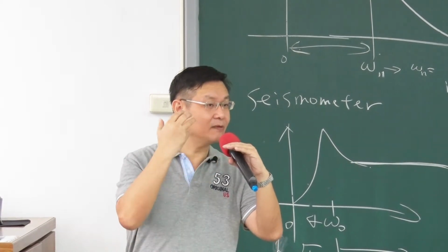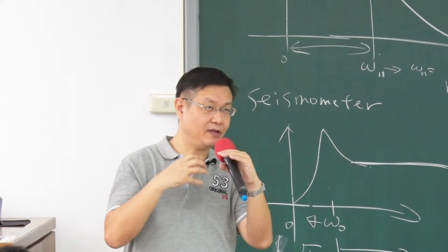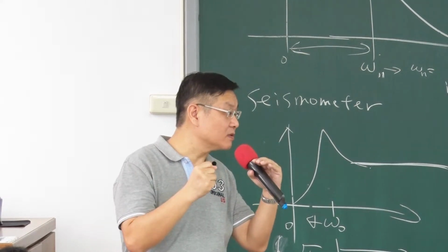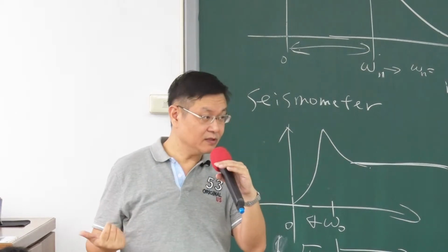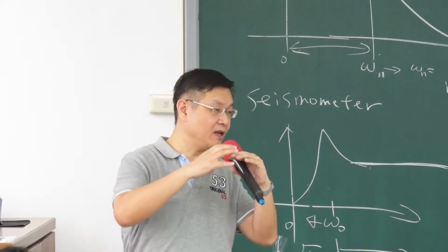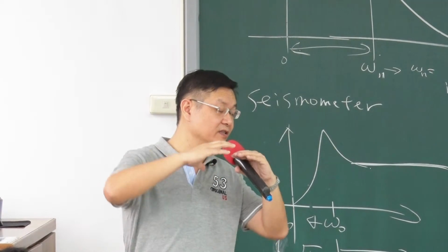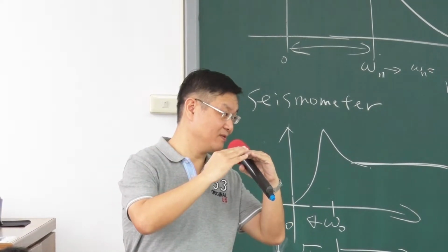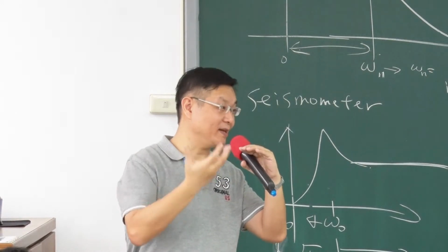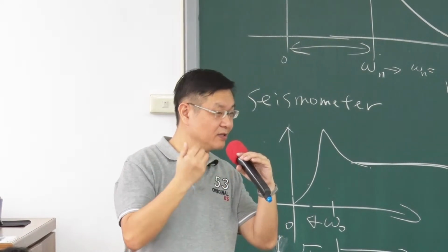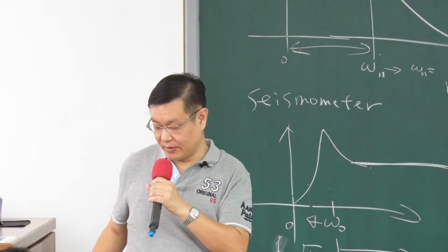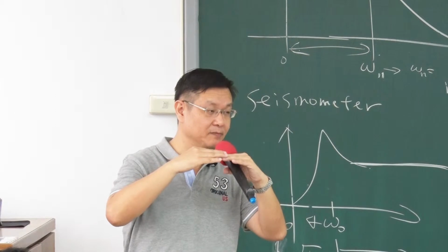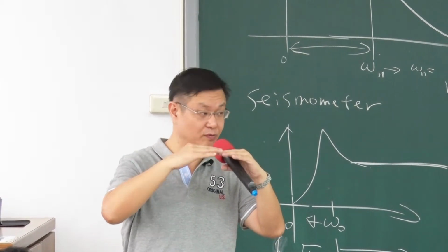You can consider it like a mass. If I have a large mass and you give it a force, the acceleration will become small, right? The same thing applies here. If you have a larger moment of inertia and you give it the same bending moment, the beam deflection will be small. It sounds like a large mass. So you can consider the moment of inertia I as a structure property. It's not a material property; it's a structure property.